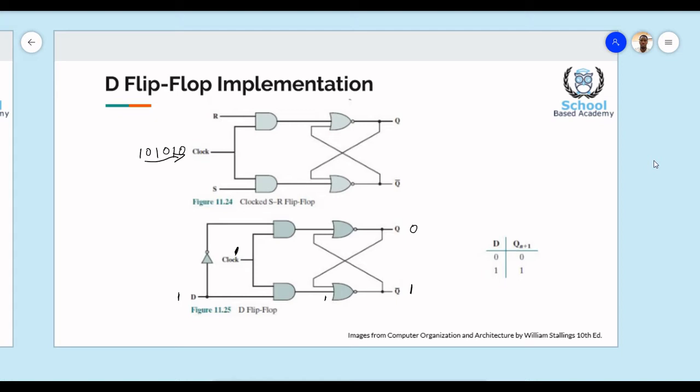We take the value of the current state of the circuit, 0, and pass that into the NOR gate along with the value of 1, and what is going to happen is that our output value here is going to change to 0 for not Q, which will force a change of 1 into our Q output value, the value that we take, the asserted value.